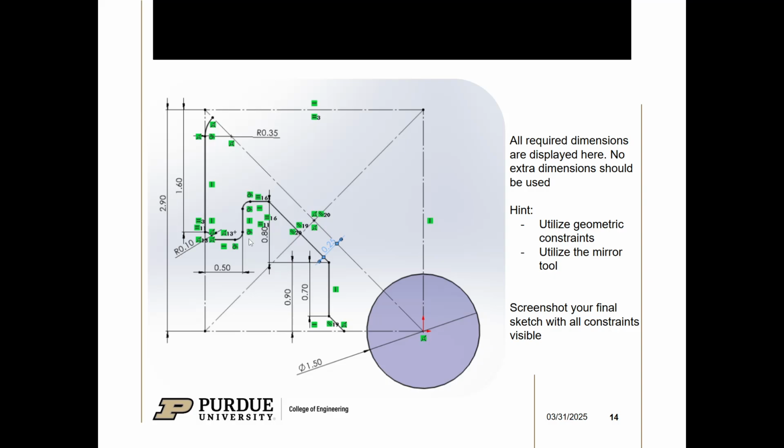What you could do is make a very simplified geometry of this. You could omit all these round pieces and then get this fully constrained. And then you can start adding more complexity, right? You can sketch it without these arcs and then add them later. And then, making sure you're adding the geometric constraints along the way should allow you to fully define this profile.